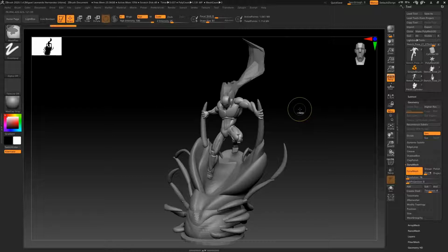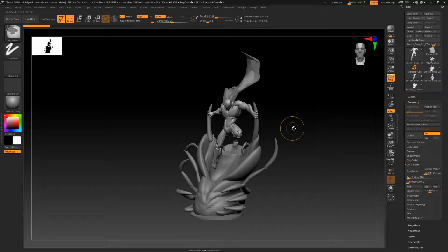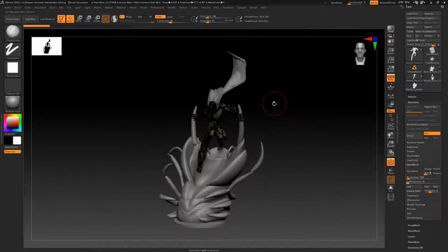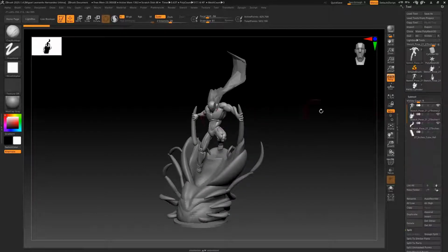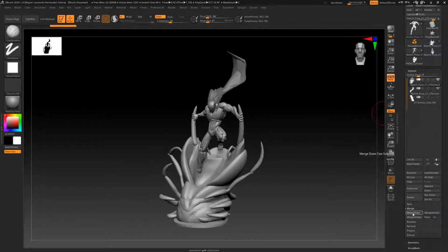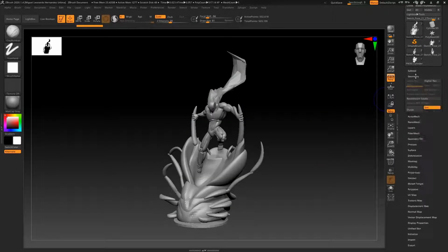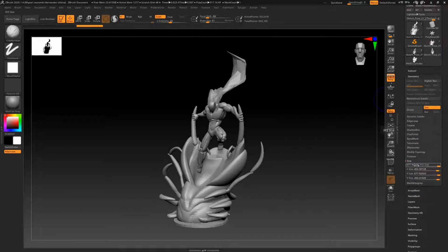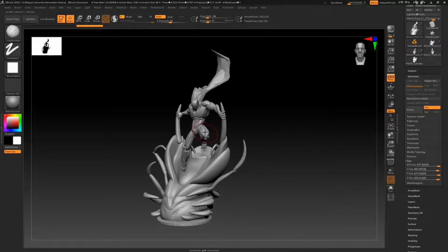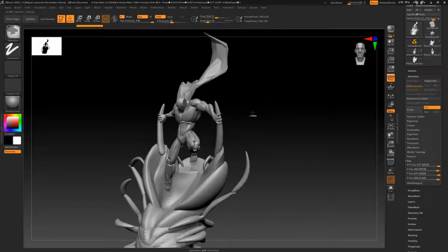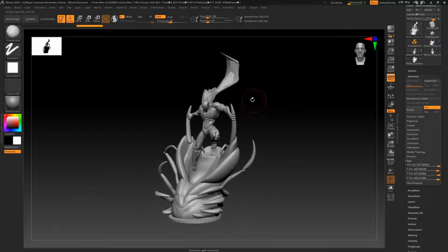So for that reason, I always want to keep this model as a scale, save this model as a final scale, and go here to geometry size and keep this number, because when you finish your model working in a comfortable mode here in ZBrush, you can resize your final model with your scale reference. So I recommend this because, as you can see, we have a few problems working on huge files.